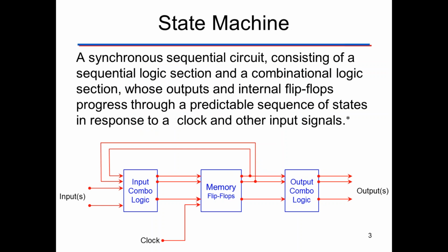And if we take a look here, I want to move on to StateMachine. Here we have a diagram, and it shows three areas: input combinational logic, memory flip-flops, and output combinational logic. What's kind of neat about StateMachines is it's the culmination of our year so far in digital electronics, in that the first semester we covered combinational logic, and you can see it on the input side and the output side over here. And then when we started our second half, we talked about asynchronous and synchronous counters.